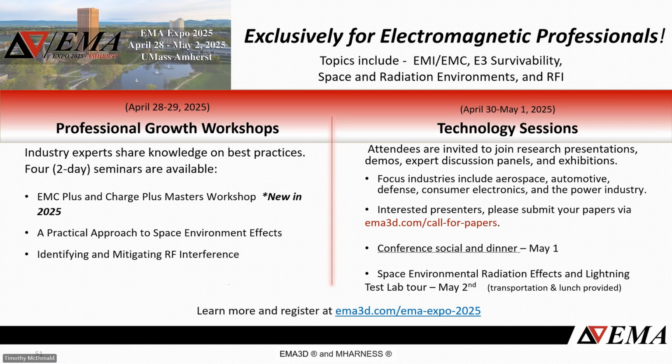Okay, thanks, Tim. Okay, next question. What is the difference between Ansys SI Wave and EMC Plus? Yeah, that's a good point. So Ansys SI Wave is an independent product. It's also available from Ansys. Ansys SI Wave is focused on printed circuit boards in planar 2.5D devices where things are laid out essentially like printed circuit boards.